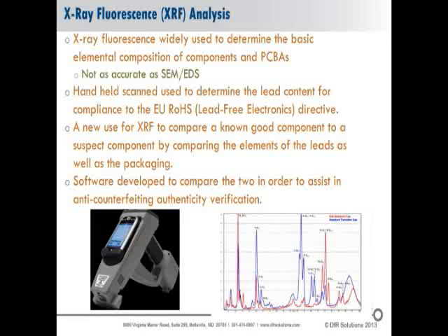These are being used quite a bit in the European Union now because of the lead-free RoHS, restricted hazardous substances. They can point at a device and quickly see if there are any indications of lead in this device without having to go to other more expensive chemical or spectrographic type techniques.